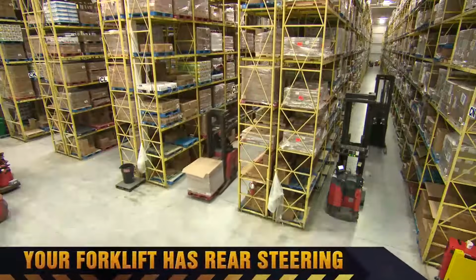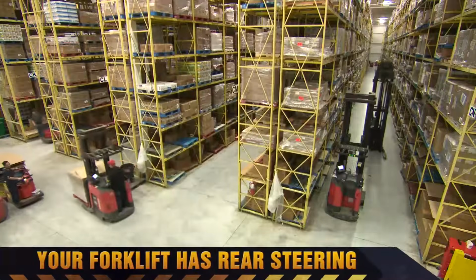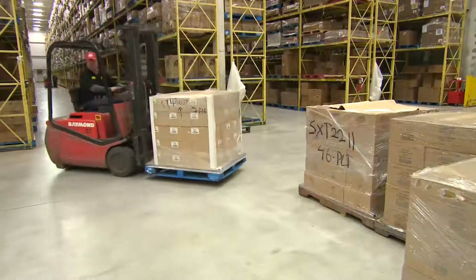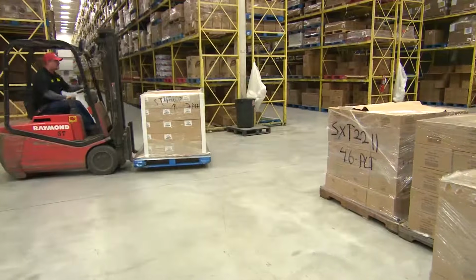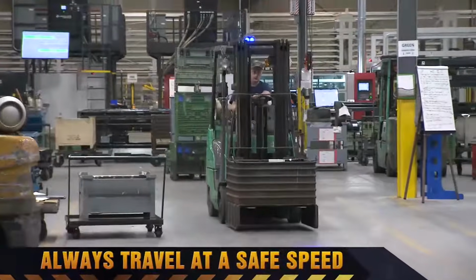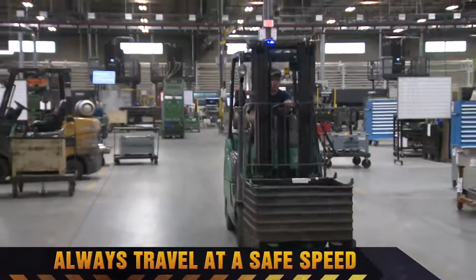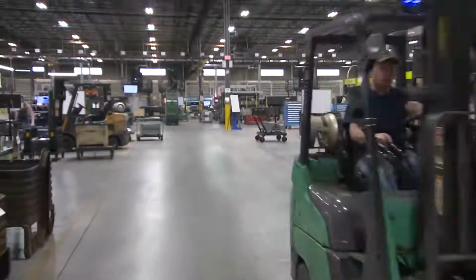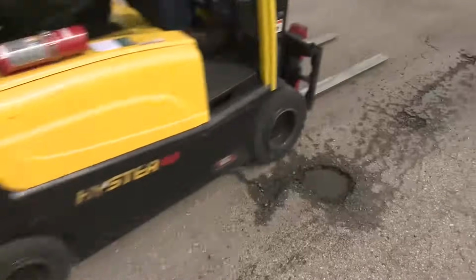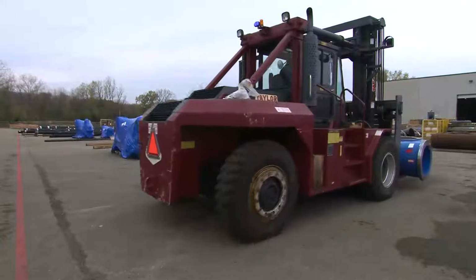Be sure you and your spotter agree on hand signals ahead of time. Remember, your forklift has rear steering and the rear end will swing wide when making turns. And if you're moving a load in reverse, the opposite is true. Don't forget to allow room for the load to swing too. Always travel at a safe speed. Determining what a safe speed is depends on what you're moving, the space available, and other traffic, as well as things like bumps, depressions, or debris. It's not easy to stop or swerve with a heavy forklift.